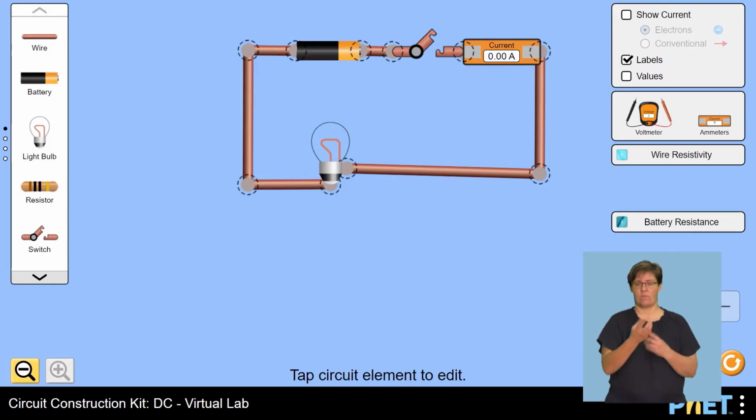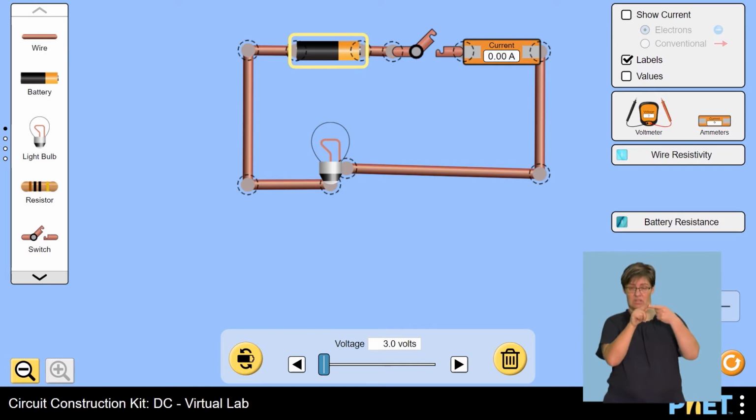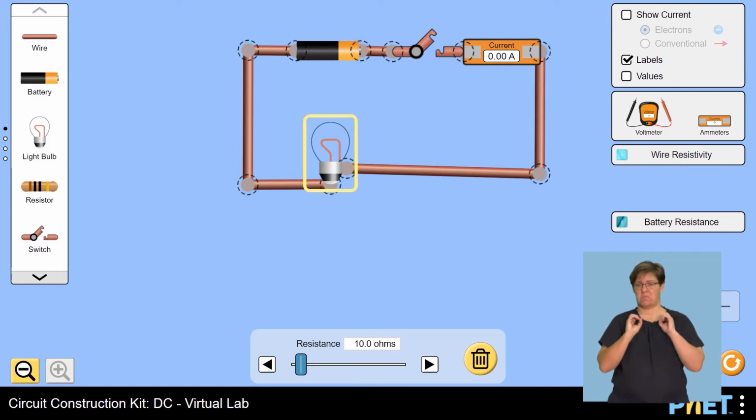So here we have a simple circuit. We've got a cell, which is a source. This cell, we will start with a voltage of 3 volts. It's an open switch, which explains why there's 0 current. And then the resistance of the light bulb we shall keep the same at 10 ohms. We just want to see how the power is affected by changing the voltage. We already know that from Ohm's law, the voltage and current are directly proportional, provided that temperature remains constant.